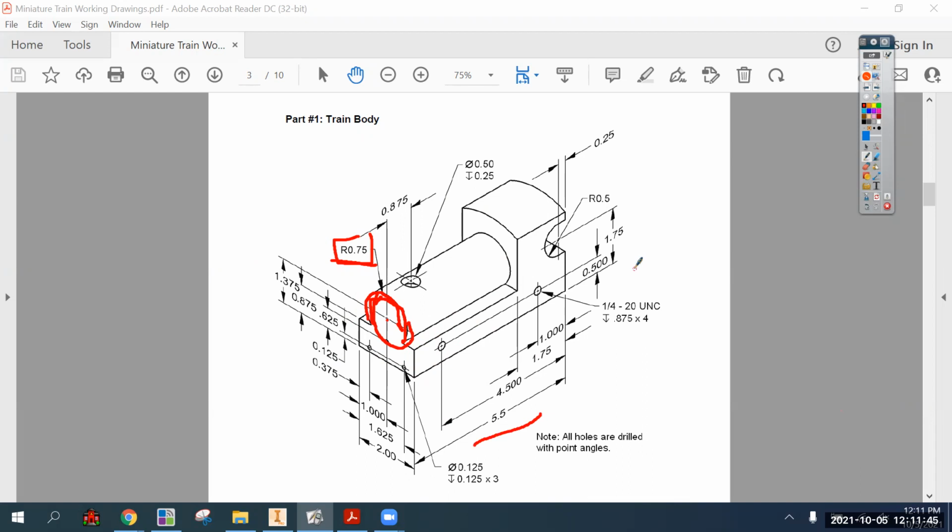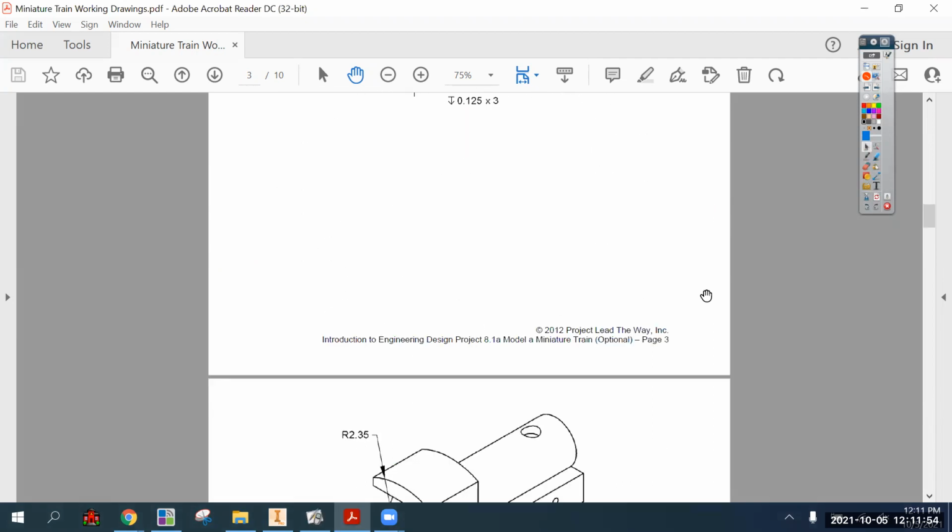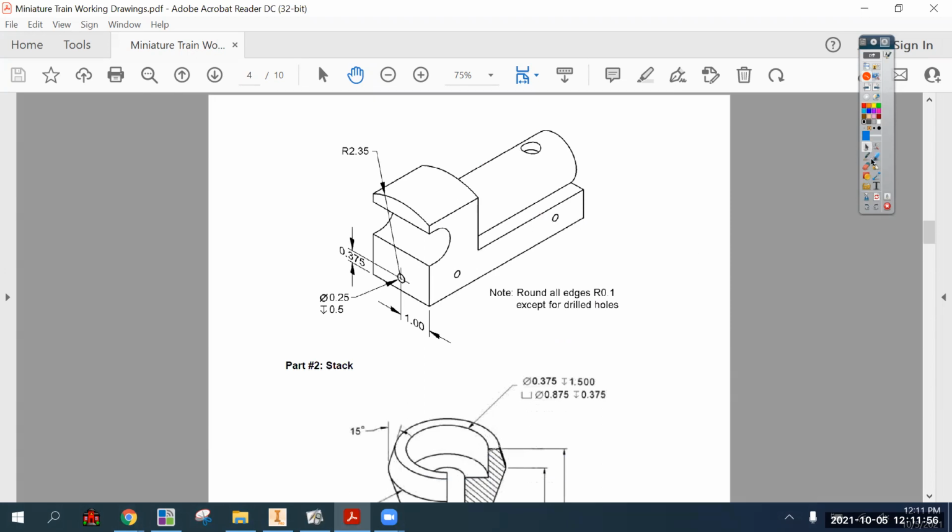So we're going to make that sketch and extrude it the full distance front to back. And then we'll add the cabin, which, in order to make it, you need to look at the second drawing, which shows how tall it is. The roof is actually an arc dimensioned from the center point of this hitch hole and extruded forward. And then there's a couple other features: the holes on the side, the hole for the smokestack, the hole for the hitch peg, all that stuff. So let's get going.